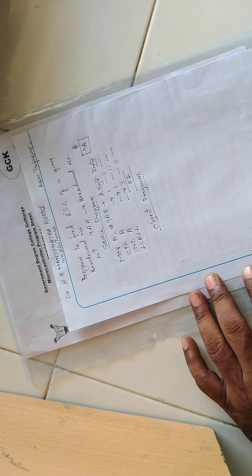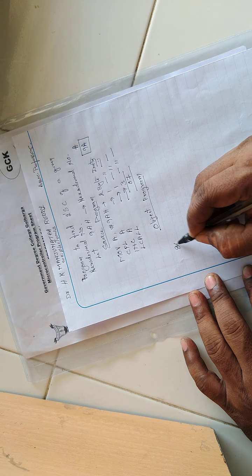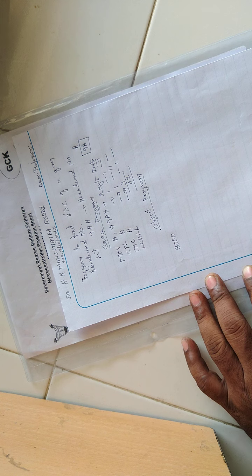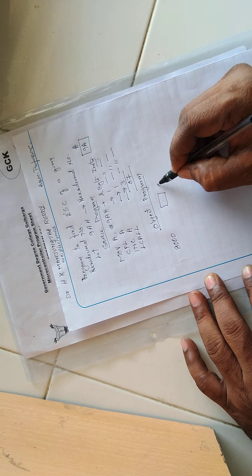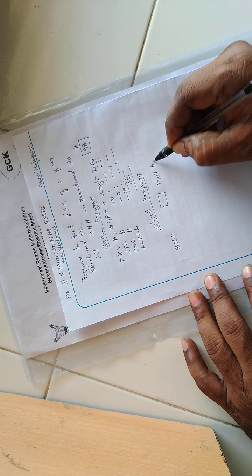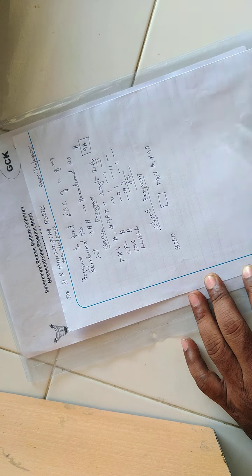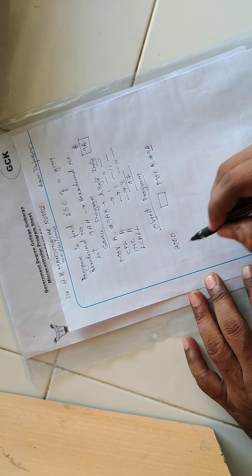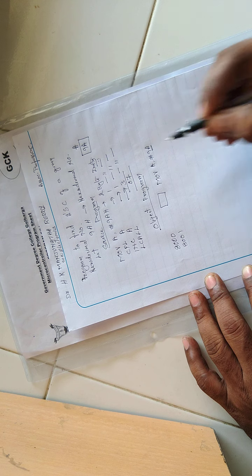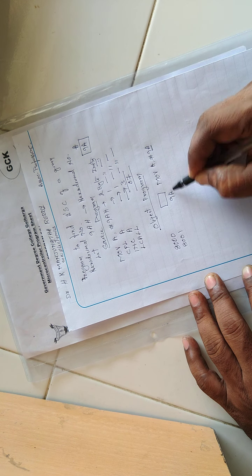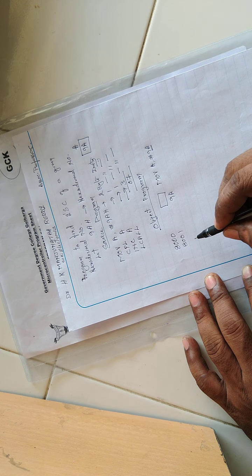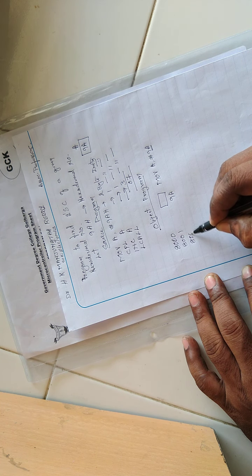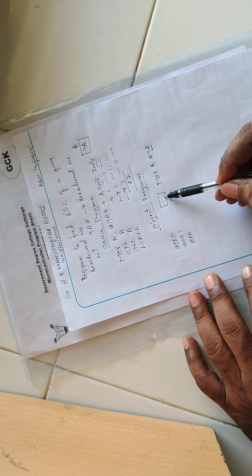In our microcontroller 8051 kit, the starting address is 8000. In this location, we shall write an opcode corresponding to the instruction MOV A, #9A. This is an 8-bit data. In the immediate location, because it is an immediate addressing mode, we have to give the data, that is 9A, or any other data that you have taken to find 2's complement. This completes 2 bytes of instruction, first byte for the opcode and second byte for the data.